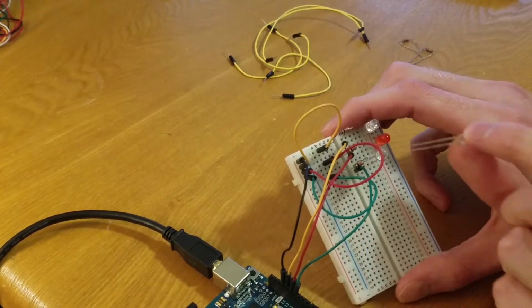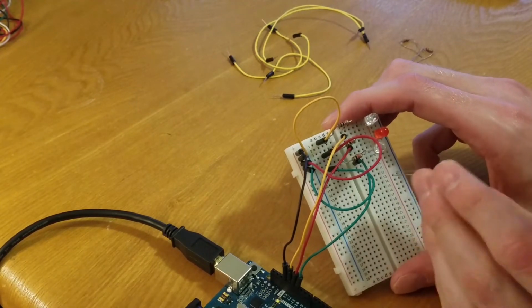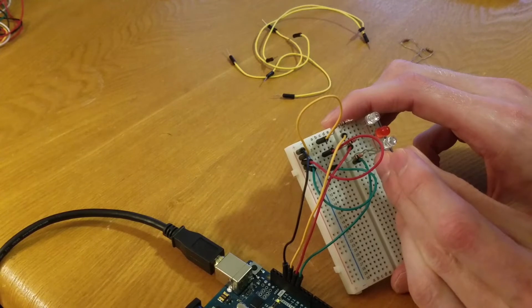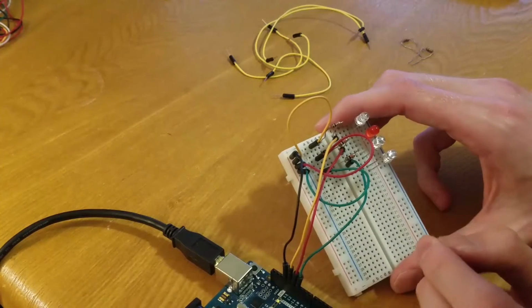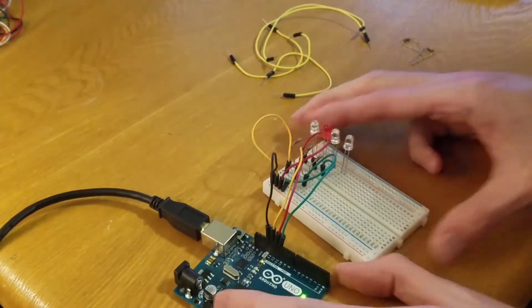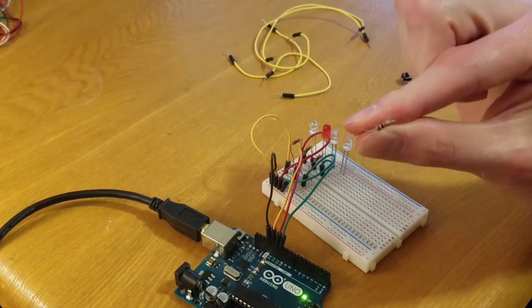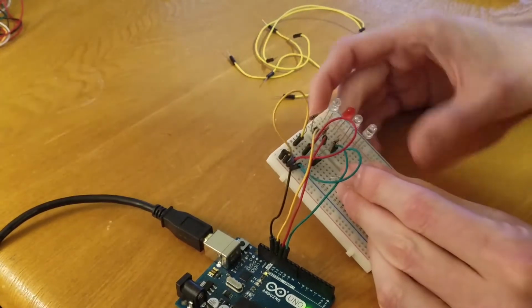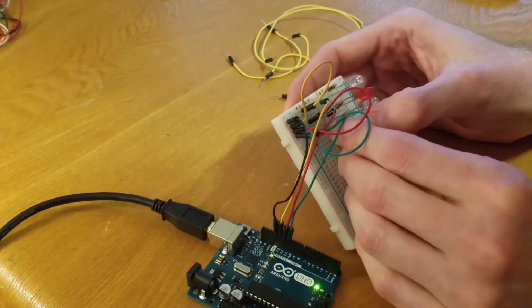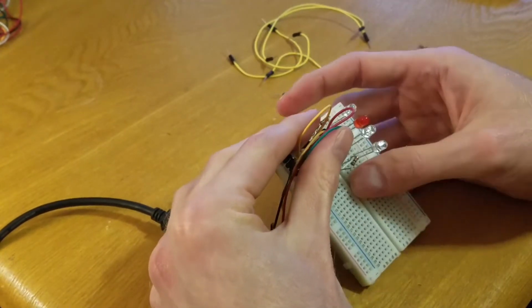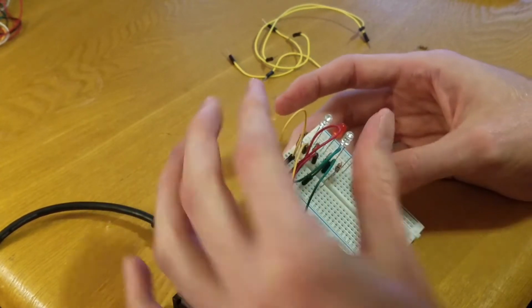So I'm going to copy what I did up here, just move a couple of lines down. My long anode line of my bulb is going to go, let's see, so it's 8 and 7 was the previous one, so we're going to skip down. Long line's going to go on line 11, short line on line 10. Okay. Red resistor, which is the 1K. Okay, that's going to go on the top line, and we'll repeat the same thing we did before. So line 10. You can kind of see that it is horizontally on line 10 in between column 2 and 3. Okay, red goes towards the right.